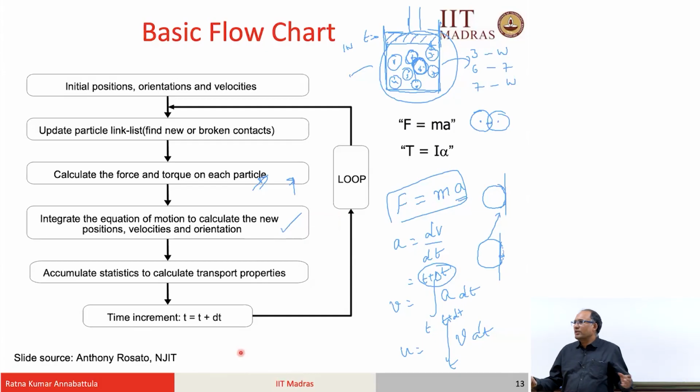So, what we are doing is, these particles move, and you monitor the position of the center of the particle if it is a spherical particle. You realize that these two centers are so close that there is an overlap between the particles. Because of the overlap, there will be a contact force generated between the particles, and that contact force will push them apart.